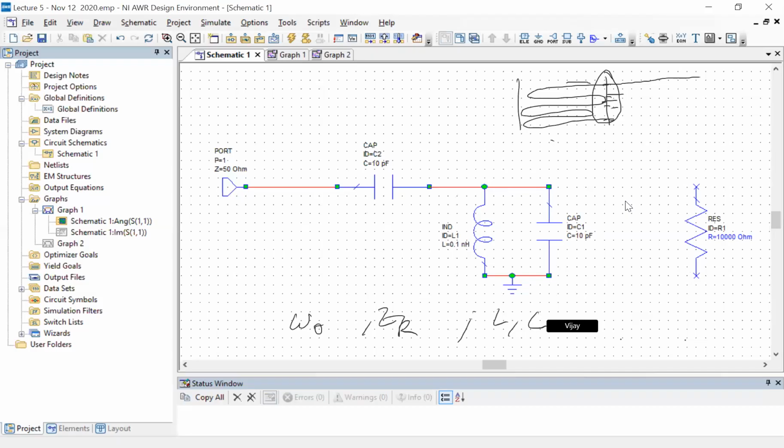I was saying two things. One I was saying is that typically you already know this frequency, right? This is something related to whatever you're trying to do. So this is fixed. Then how to make a resonator which has a value of resonant frequency omega 0, but has different values of ZR, then you just have to change L's and C's. That's what I meant. It's not that you cannot do it. You mentioned something about a constraint added via the port. I added by what? Sorry? The port being only 50, always being 50 ohms.